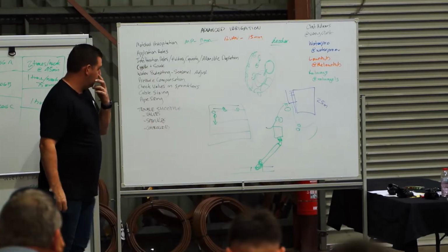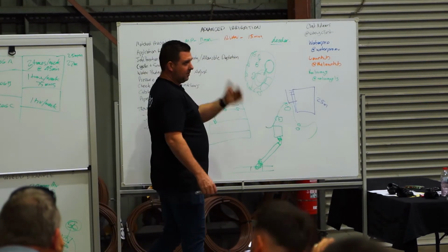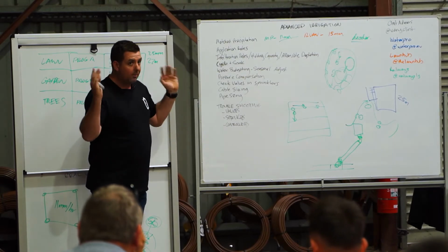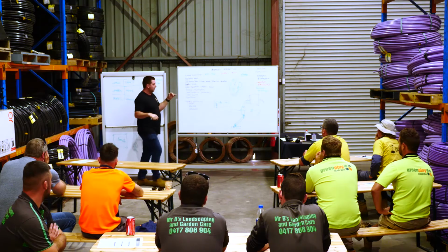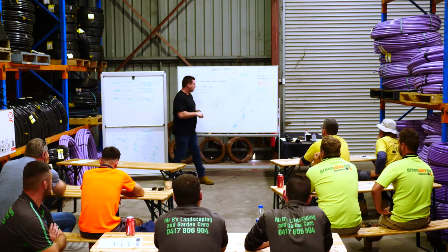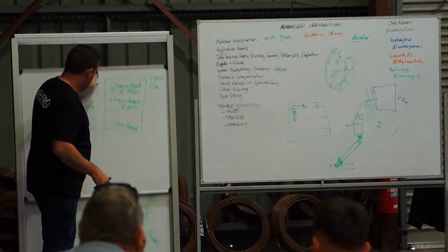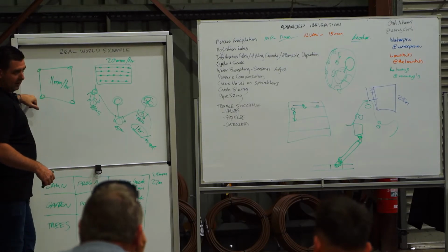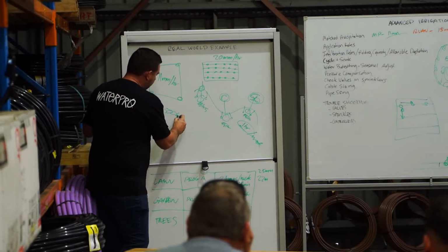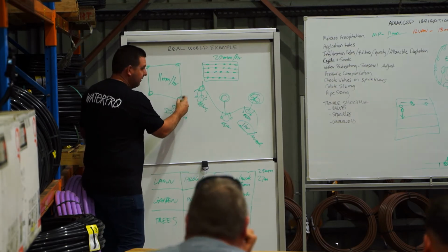But it's also important to remember that there's a velocity there. We lose pressure through everything, so from the start of a system, through the backflow, through the master valve, through the ball valve, every elbow, the sides of the pipe, the water rubbing on the pipe as it moves through it, going into a manifold, the elbows in the manifold, through the valves, everything that happens loses pressure. When we design an irrigation system, we know, these sprinklers need 280 kPa at the sprinkler, right? So we talked before about a 500 kPa pressure reducer at the start of the house.